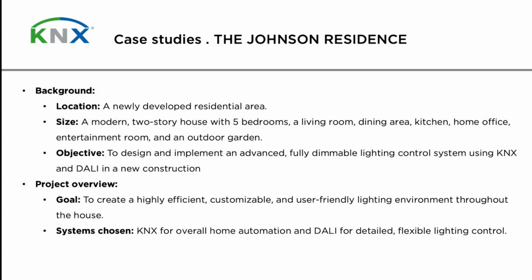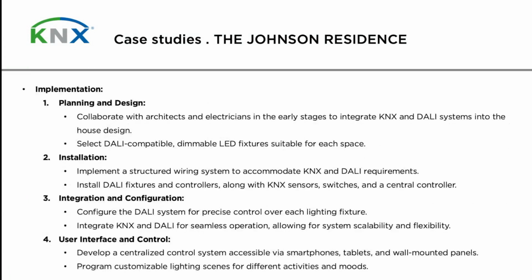Another project. In this case, this is a residence, a villa. A new villa, quite big. Everything is DALI for lighting control, including just a single relay to switch on a single light. KNX is used as a backbone. If we want to control lighting fixtures, we go through DALI. If we want to control the air conditioning, we go through BACnet. And if we want to control the shading, we go directly with KNX because we have shading actuators in KNX.